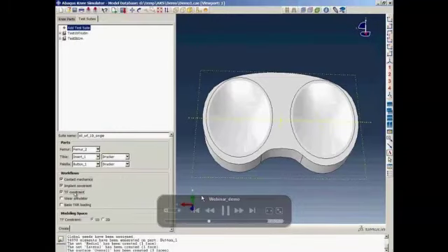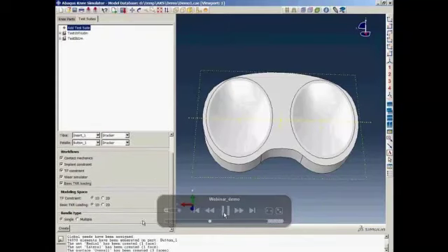And the user can select which workflows to be included. For the tibial-femur constraint workflow, because we have representation of the soft tissue, the user can select to represent the soft tissue as either 1D or 2D elements. Similarly, for the basic total knee replacement loading workflow, they can choose the modeling space for the ligaments, and for the quadriceps, they can model them as either a single bundle or multiple bundles. In this case, we chose the simplest option so that the models will be generated in a reasonable amount of time.